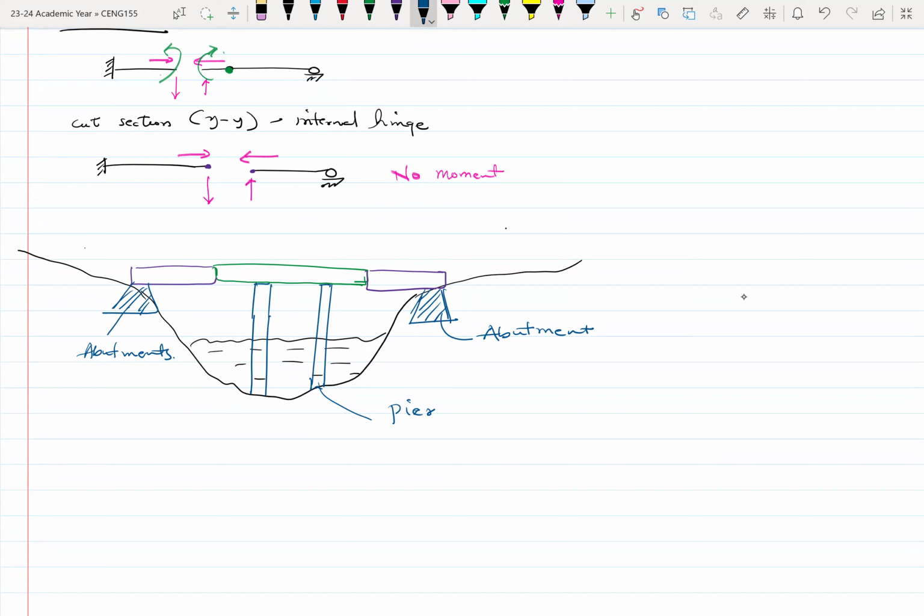The reason is that, not in all cases, but in some cases you want it to expand and contract. For example, if you are using steel members as your bridge, you want that option, because if you do not allow expansion and contraction of the bridge, for example if there's an increase or a reduction in temperature, all of these things can happen. You would want to ensure the expansion, otherwise stresses will be built up in your bridge and these can lead to cracks in your bridge construction or the bridge usage.